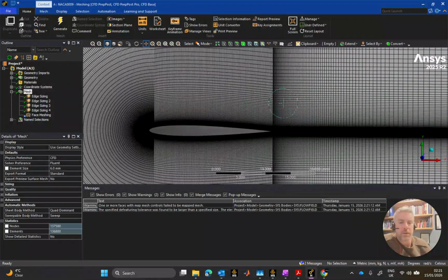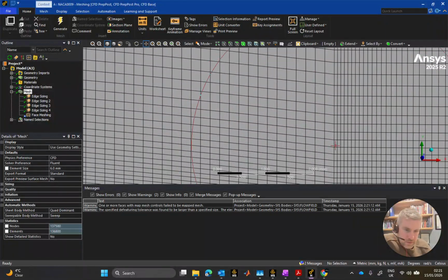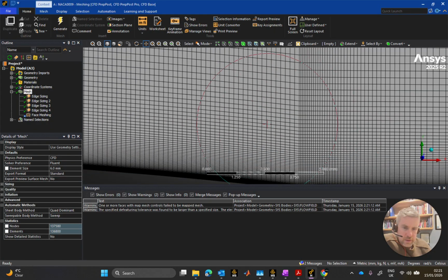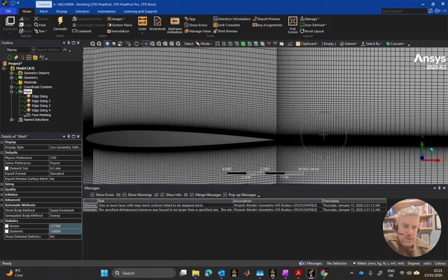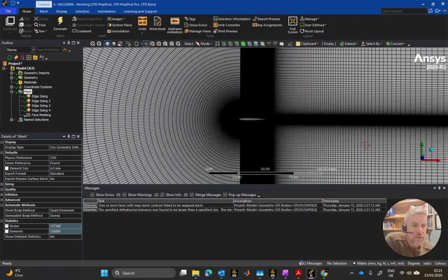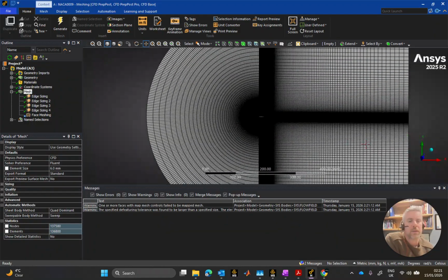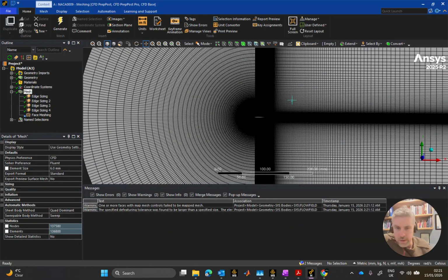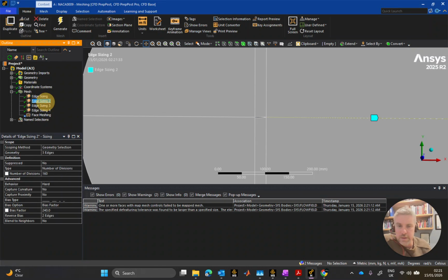It's not really having the immediate effect that I want. This one coming down as much as it has really killed it a wee bit, and it's very badly meshed. So I'm going to bring this back up again to 220. I'm going to reduce this bias factor again slightly, maybe down to 180.